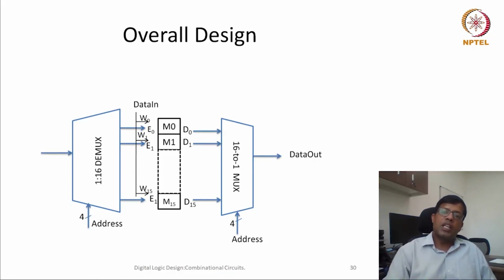We can say that this data out we are not going to read, so we can have another AND gate here so that this data out would be read only if my read signal is 0. So this is how, whenever a design question is given, we have to think over it. We can break it into smaller functionality and work on all those functionalities independently to come up with a complete design.